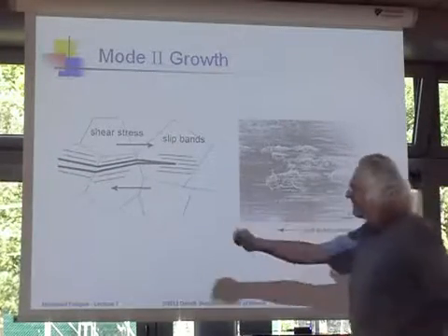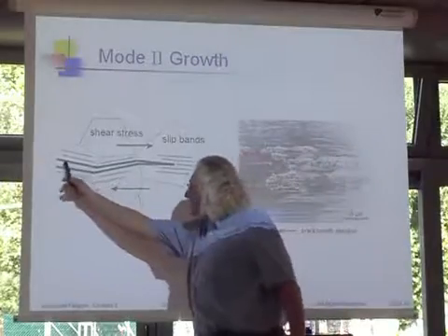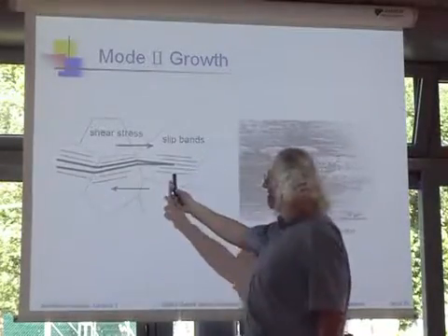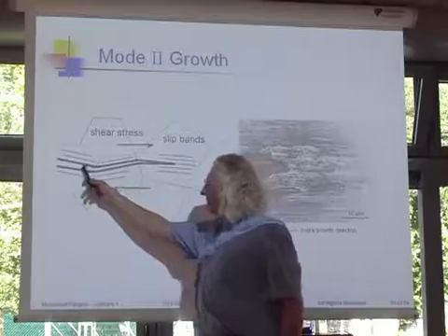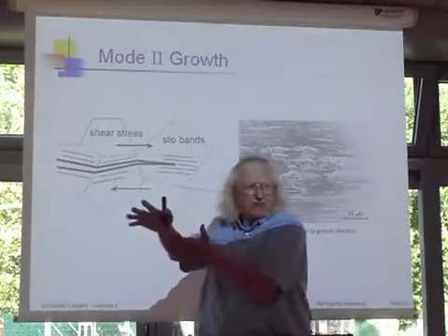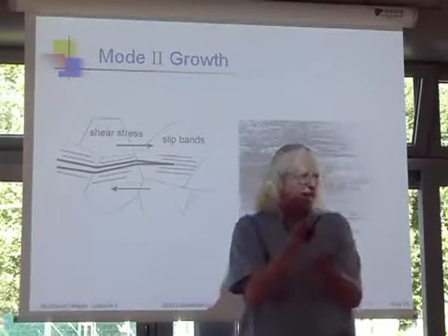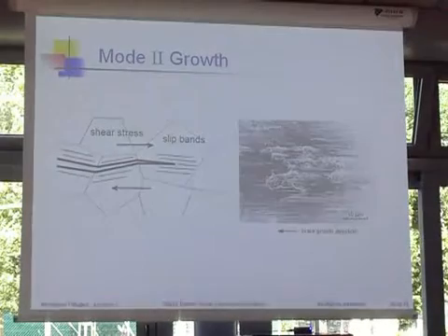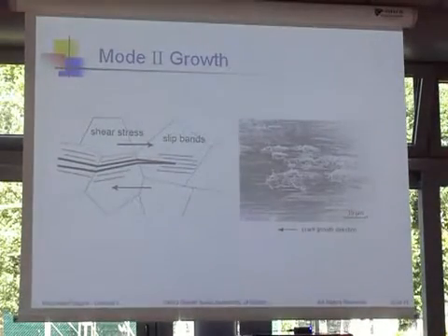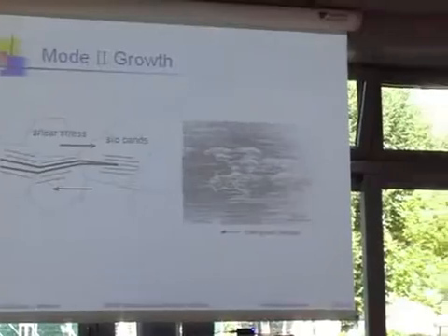Imagine if I take my little cartoon here, I'm trying to shear this back and forth, and again I have a cracked surface which is not really flat, but it's trying to shear itself flat. Look how difficult that is, right? That's really, really hard to do compared to opening this up in tension. So what you will find is that crack growth in shear, long crack growth in shear, is very, very difficult. Right? The rates really are slow.